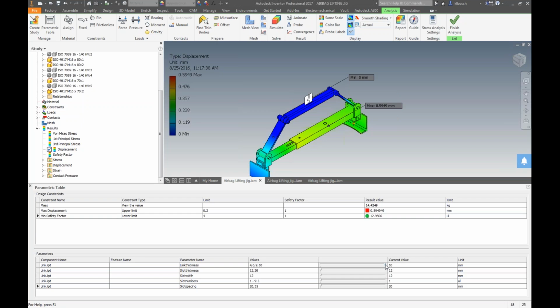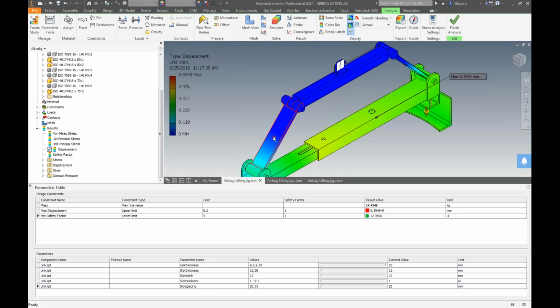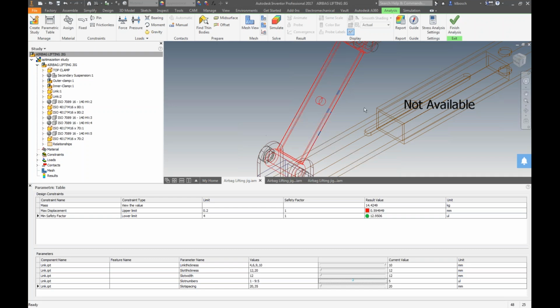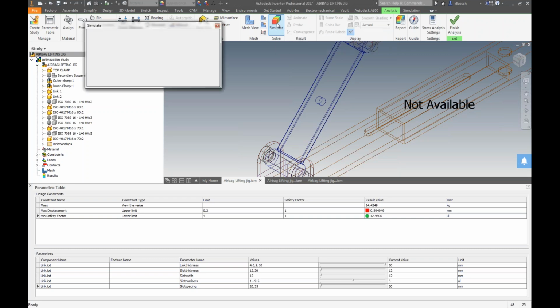And if I want, let's say, our number of slots, so the amount of slots that we've got in an arm, if I simply take my little slider here and move it off to the side, you'll note that it says, hey, this is not available. That simply means that this iteration hasn't been calculated yet. Well, I can come right back to simulate, and I've got some options.